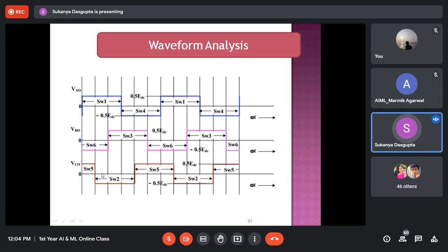Okay, for this time period, look at the timing diagram. 4 is not working because SW1 is working, right? 3 will be under operation exactly at this 120, and 5 will be exactly after 240 from the first one. So this is 180. 180 plus 60 means this is 240. So if this is 240 and this is 60, because 5 and 2 are complements of each other,